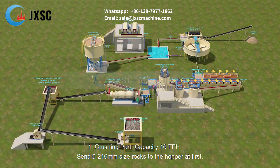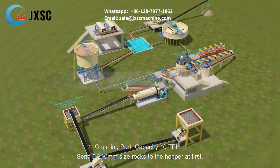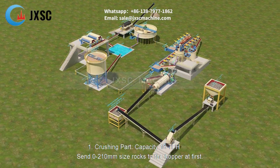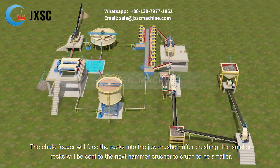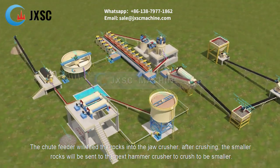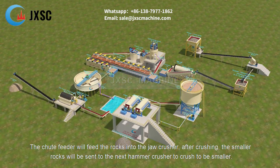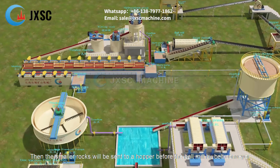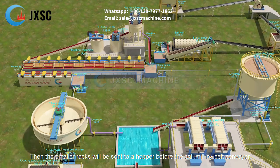1. Crushing part, capacity 10 TPH. Send 0 to 210 mm size rocks to the hopper at first. The chute feeder will feed the rocks into the jaw crusher. After crushing, the smaller rocks will be sent to the next hammer crusher to crush to be smaller. Then the smaller rocks will be sent to a hopper before the ball mill by belt conveyor.